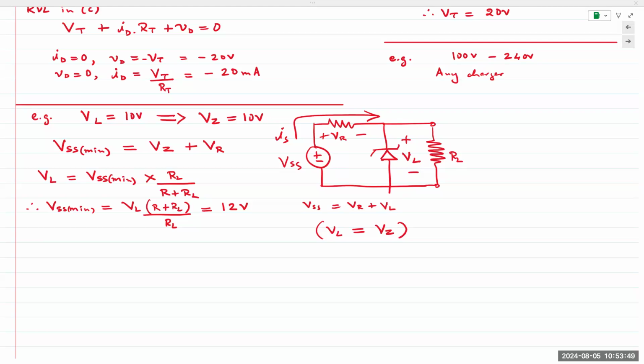So again, the answer is you will see new circuits all the time. The approach remains the same. You simplify it as much as possible, and then you logically think about which equations would fit. There are only 3 equations. If you just took the class 201 with me, then you know what I'm talking about. But as a reminder, I will tell all students in 201, it seems like you learned a lot of analysis techniques, but there are only 3 equations in the entire course. Ohm's law, KCL, and KVL. That's it. All other techniques are based off of these 3 analysis techniques.